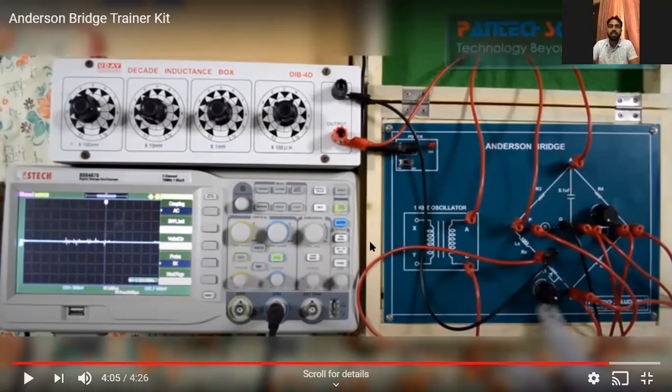So this is basically the motive of today's lab. I hope you all might be able to understand what is basically the Anderson bridge and how it is different. It has a very easy tuning as compared to Wheatstone based on resistances. If we are using a number of resistances, they drop some voltage, and because of that drop, power losses are there. So always using a device which absorbs power is not good. The better thing is to use a device that should not drop losses. So that's why we are putting some improvement.